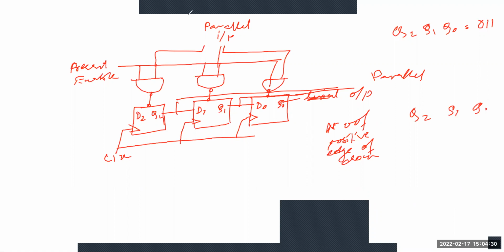So here again you are watching that this circuit consists of 3 D flip flops, and the output is connected as the input of the next D flip flop, and all the flip flops are synchronized. Now in this shift register, we can apply the parallel input to each D flip flop by making the preset enable 1. So here we can apply the parallel inputs to the preset or clear, you can say, and these two are asynchronous inputs. In earlier cases we have seen the synchronized input, but here we are watching the asynchronous input.